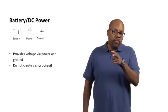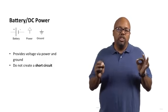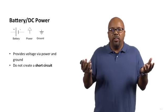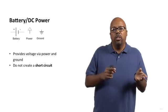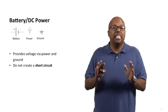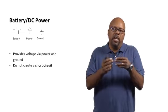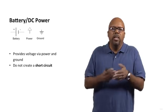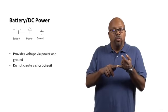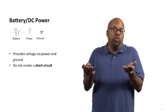One other note: never create a short circuit, specifically a short circuit between power and ground. A short circuit is when you accidentally connect 2 wires together. If you were to short power to ground, if you took power and ground and wired them together by accident, then let's say power is 5 volts, so you have a 5-volt difference between ground and power. But the resistance is 0. If you run a wire, you have effectively no resistance.